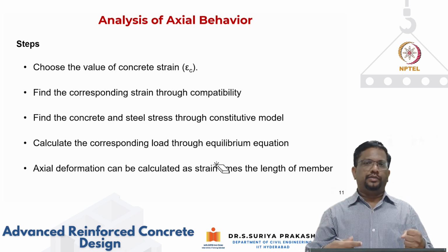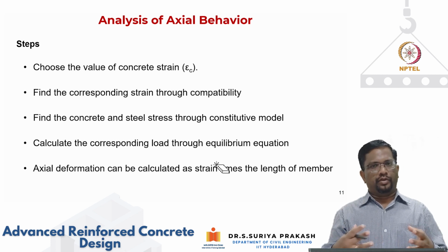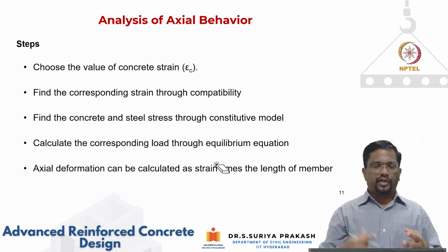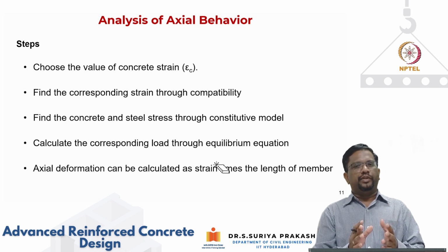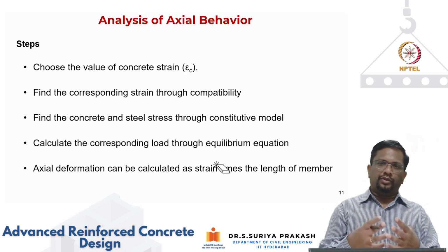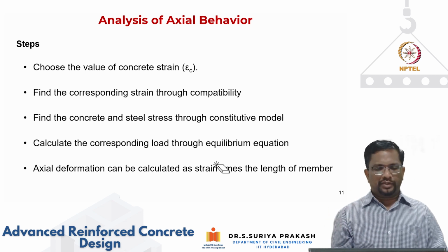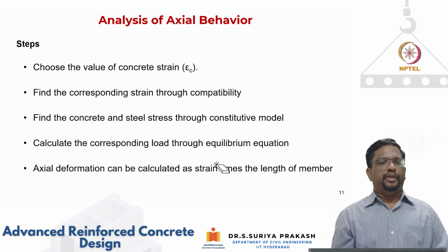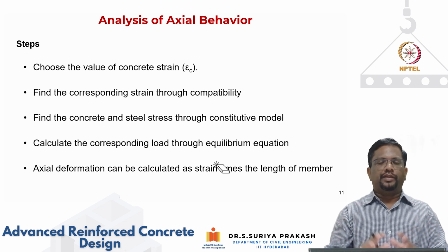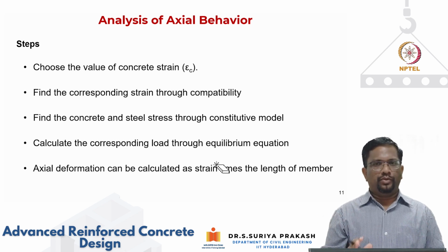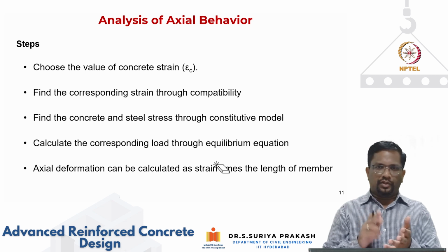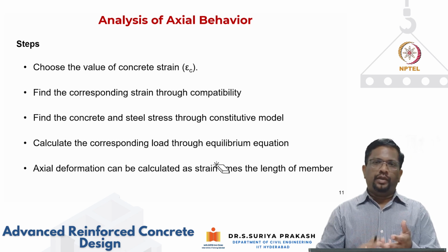Concrete members usually also have ties or transverse reinforcement, and some influence will be there. It is going to confine the concrete core, that effect of confinement of ties, all of which we'll discuss in the chapter on column behavior. But for now, the tie is not going to play a major role. The majority of the load resistance is going to come from longitudinal steel and concrete.